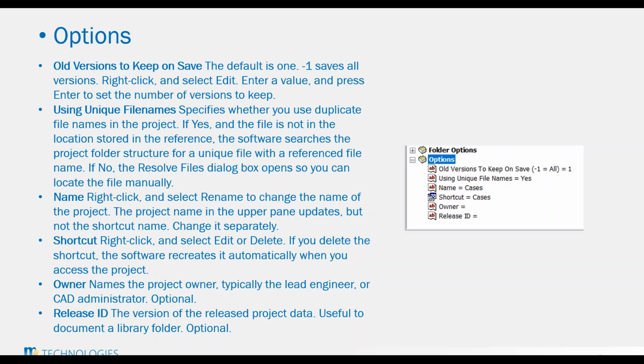And the last one here is the unique file names. You want this to be set to yes to make your life easier. If you set this to no, it allows you to use multiple files with the same name. And I think that's pretty dangerous.